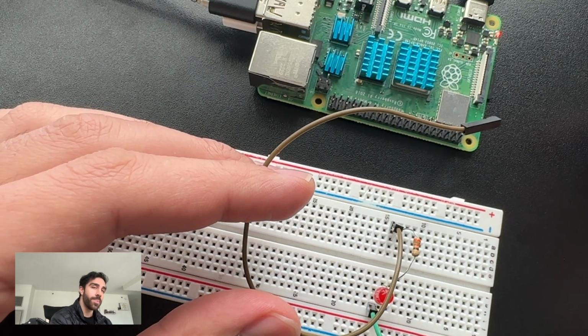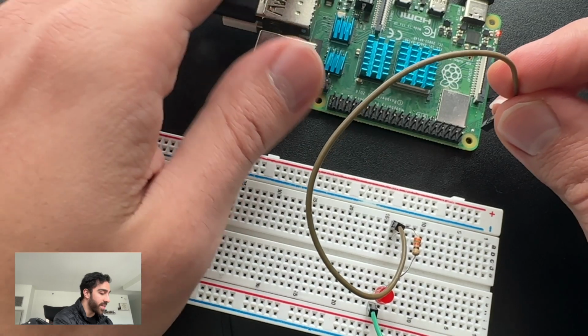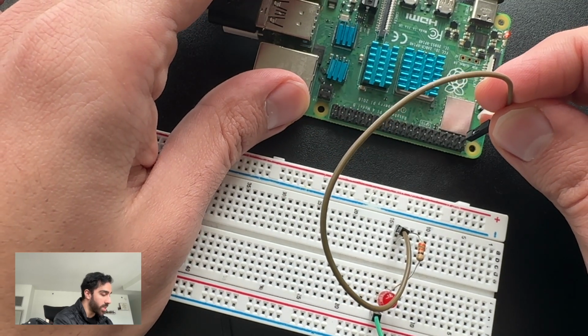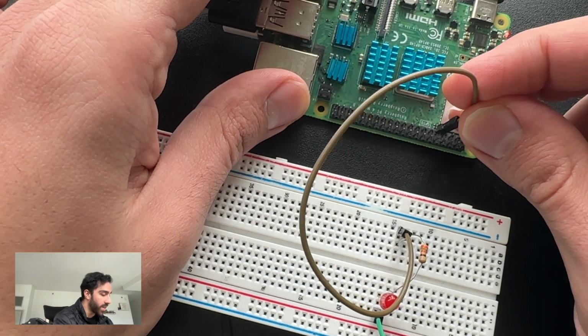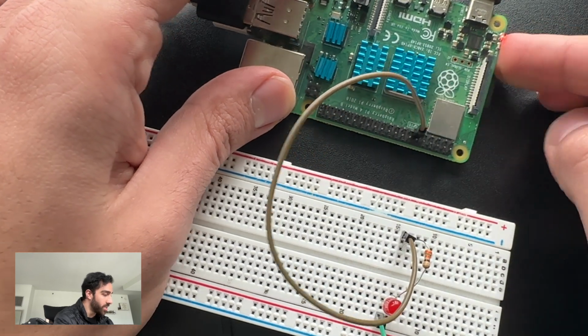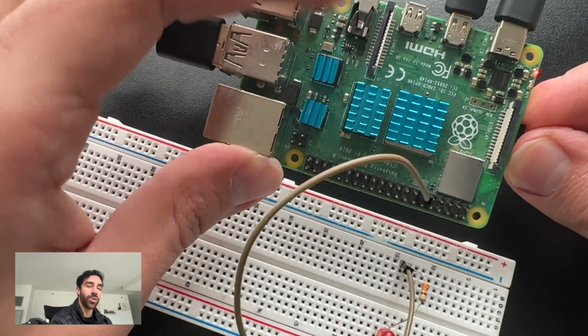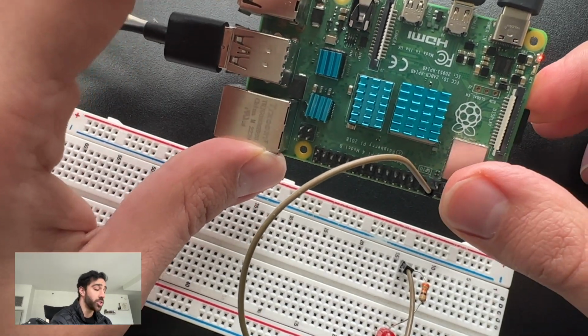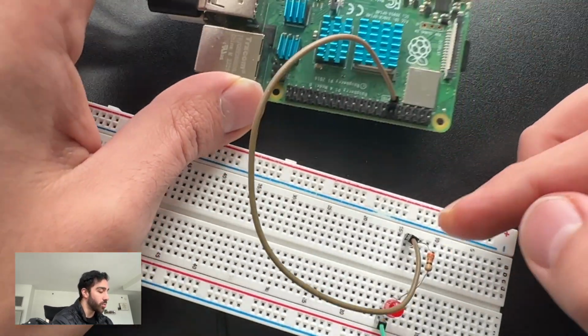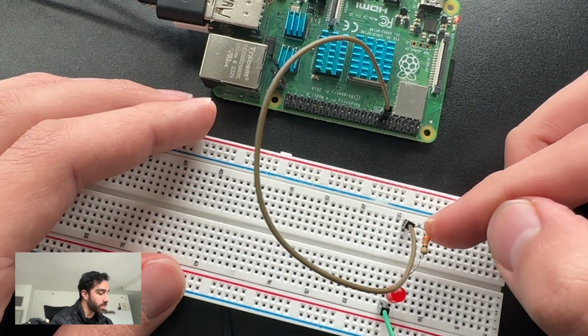We're going to be using GPIO 17. That is the 6th pin from the top. So 1, 2, 3, 4, 5, 6 in this back row. So you see we are using GPIO 17, and if you're confused about that, you could just search pins on the Raspberry Pi online and it'll show you which one is GPIO 17. So that goes to the input of the circuit.